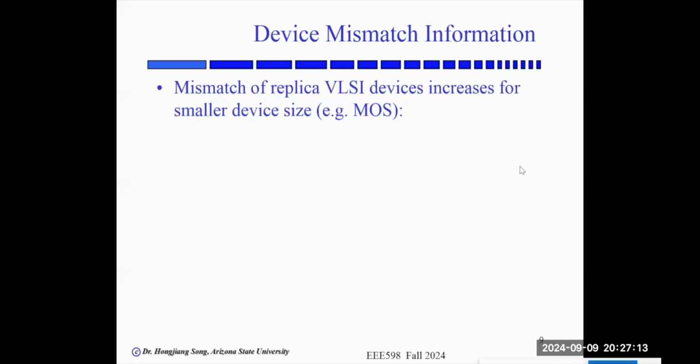Since the quantum simulation will not be able to catch the variation of the same type of device, this is where type 2 simulation needs to kick in. So here is some very important information about the mismatch of the same type of device. The first one is that for most devices, both VT and beta are inversely dependent on the size of the device itself.